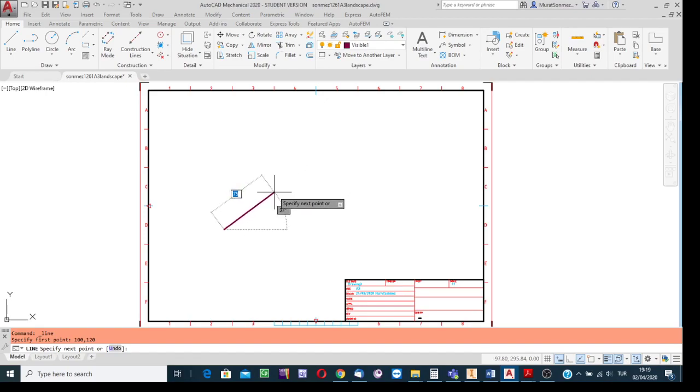Okay, close this parenthesis, meant to remind you of such tricky important things. And then turn back to our case. In this example, we input the coordinates of the starting point relative to the absolute origin, and now it is the following stage. At this stage, the program, using this simulation, notifies me that I need to write the length of the line. In this example, say that the length of the line is 80. Into the box write 80.